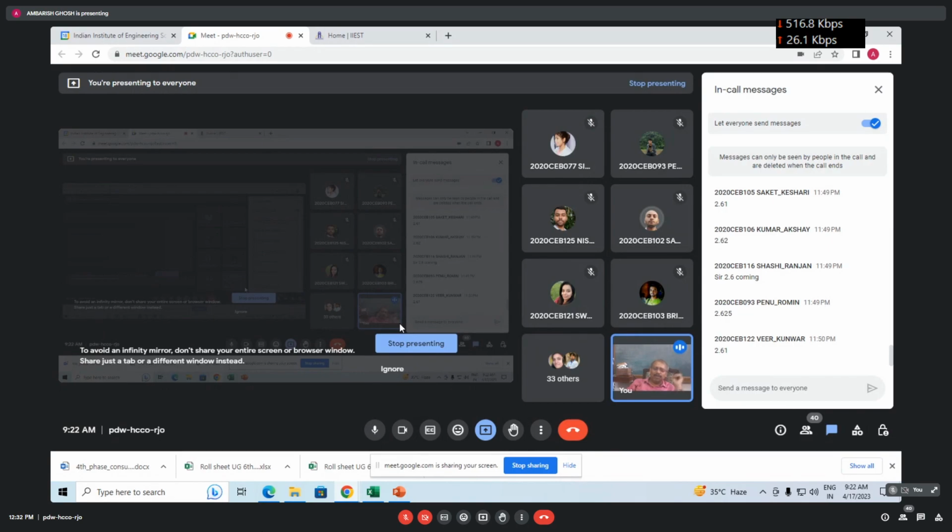Then you calculate from the given Y value, either 5 millimeter or as per IRC you can take. So you will get the H value. Fixed head condition and free head condition will be different. So after calculating that, you are in a position to get the moment also due to the lateral load.